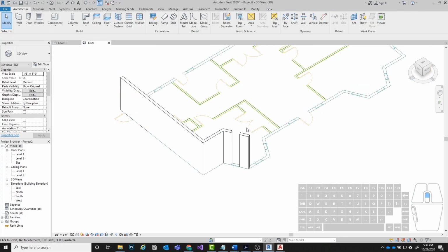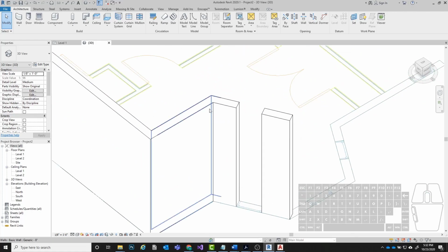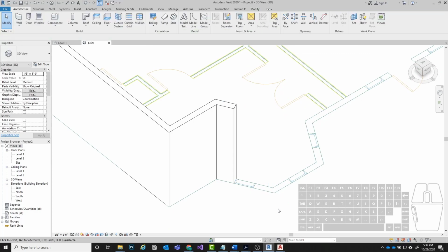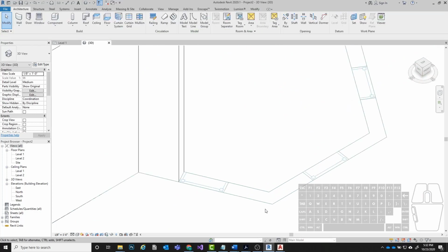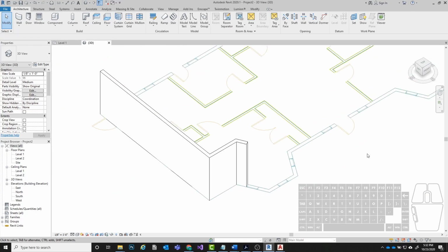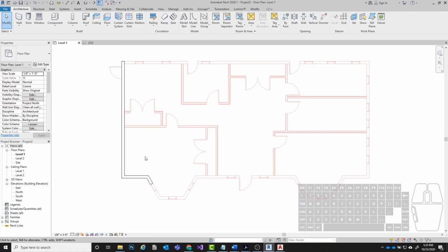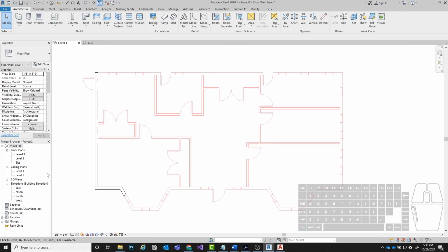So this will make more sense as we finish this exterior, but just keep in mind, as you draw in, you want to go all the way to the very corners of your wall intersections, all right? So I'm gonna go back to my level 1 view. Here is a tip. If you want to cycle between these tabs here without going up to them, the hotkey for that is holding Control and clicking the tab key. All right, now I'm automatically back to my level 1 floor plan.